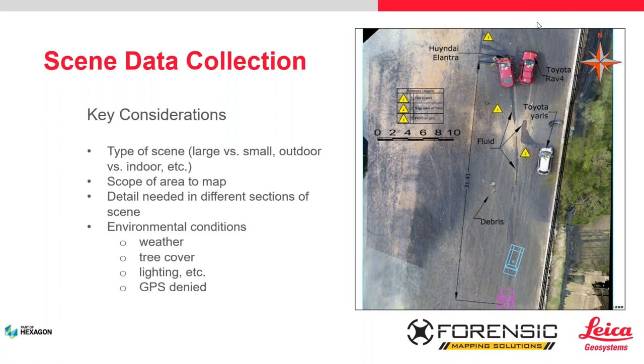So while we're there and we're going to be looking at this, large or small, the time that it takes, some of the things that we need to be cognizant about is, when can we use this technology? So drones, obviously, there are a lot of issues because we're flying. We have a flying camera. So to do that, certain factors can cause a problem. Weather's a big one. Most of these drones that people are using, the DJI, Autel, most of these drones cannot fly in precipitation. It'll destroy the drone. And also, if it's raining hard enough, you're going to get water on the lens. There are several drones out there that are kind of weather rated, but they're very expensive, and you're not going to get the best results because of the water or snow or whatever it is on the lens.